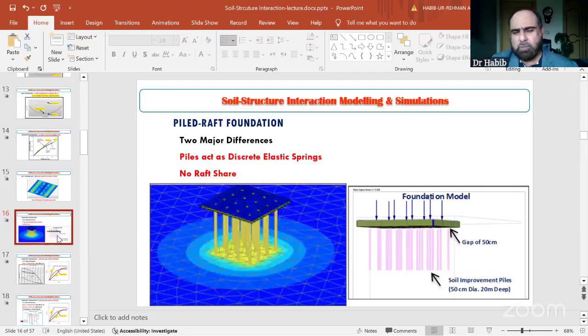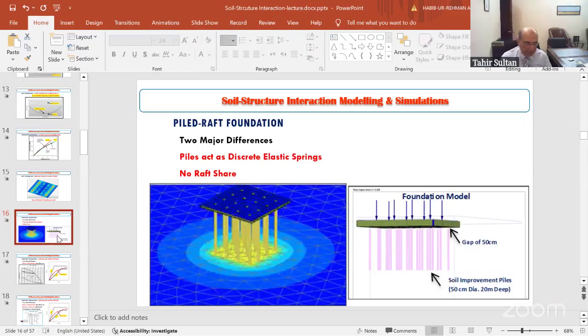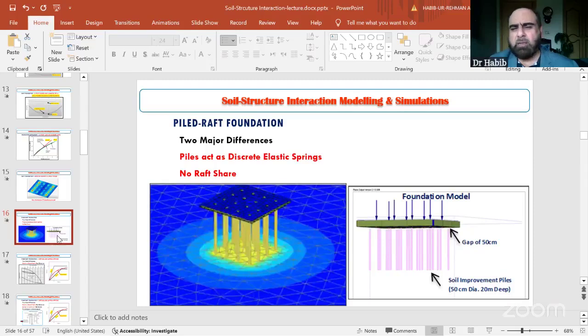The rest of the traits of the soil, or the rest of the components associated with the inhomogeneity or heterogeneity of the soil, we usually cover through a factor of safety, which we usually determine through a probability factor. If we have a high probability of uncertainties involved in the soil behavior, or the presence of different types of soils, we increase the factor of safety.